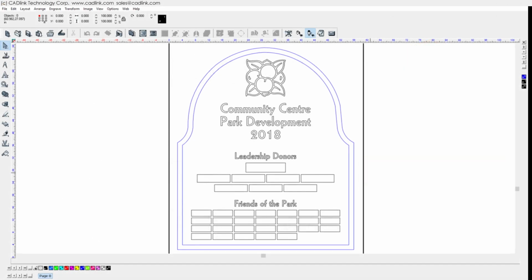The Badges feature is used to create a series of repeating designs, such as ID cards, nameplates, and so on. Optionally, replacement text can be automatically substituted for each badge, and in the case of numeric values, including barcodes, the replaced numeric values can be incremented for each badge in the series. For text that has been applied with either special effects or toolpaths, the Instant Replay feature will automatically recalculate all such operations for replaced text.